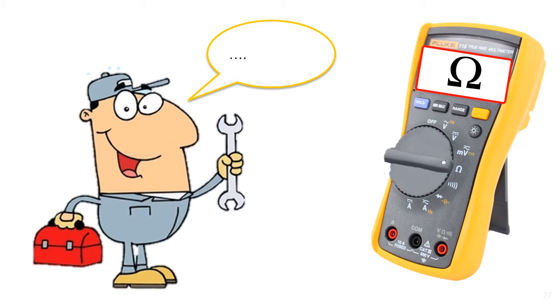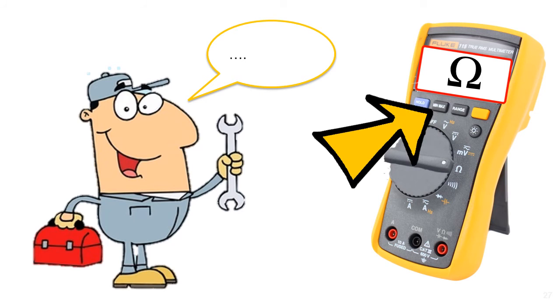While you're measuring the resistance in the CAN network, set your multimeter to record the minimum resistance and do a wiggle test on the harness. Repeat the wiggle test with the multimeter set to record the maximum resistance. The resistance should not change when wiggling. If the resistance does change, there's a problem in the harness or connectors.